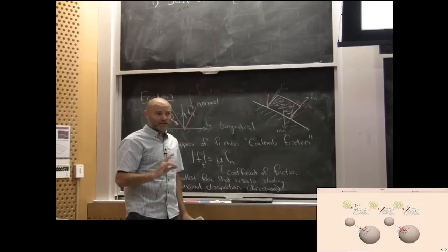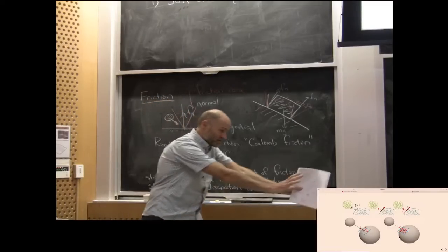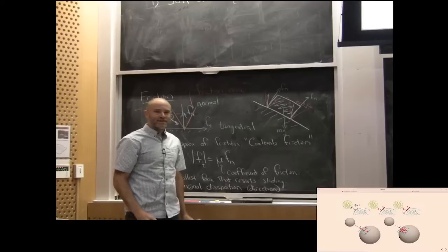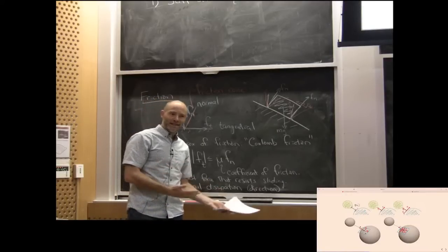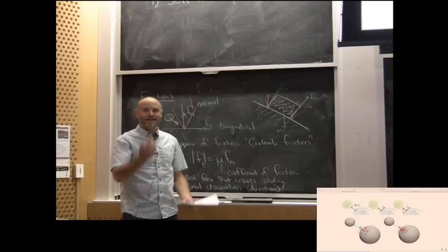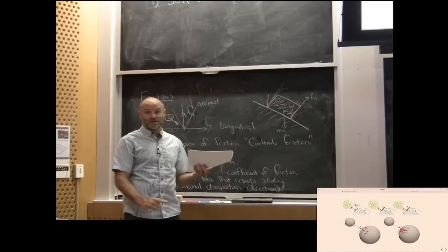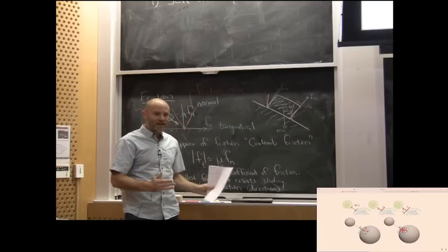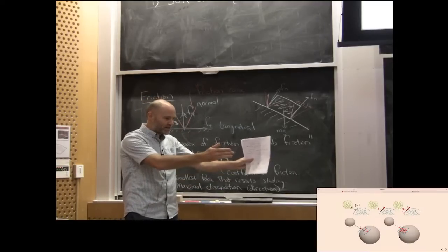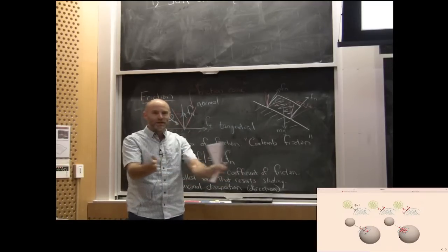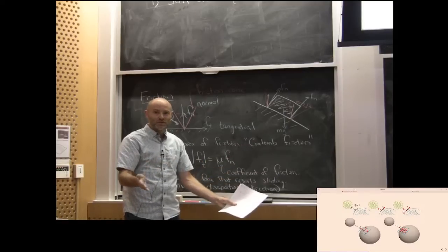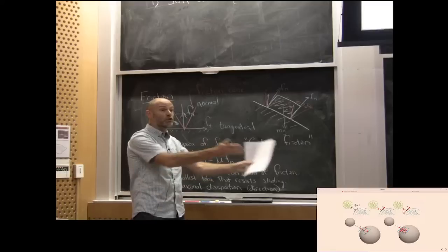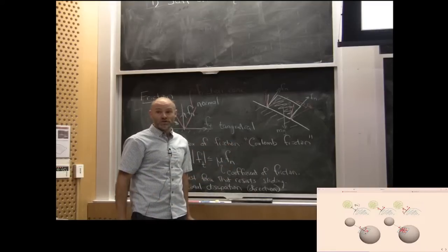Here's the problem now. If you go to push the table, some of those feet might be in sticking, some of them might be in sliding. Depending on the normal force, you don't know what the friction force is. So the rules of rigid body mechanics will not tell me if the table goes straight or turns left or right. All of them are possible solutions given the governing equations. They do not give me a unique solution to the differential equations I generate.